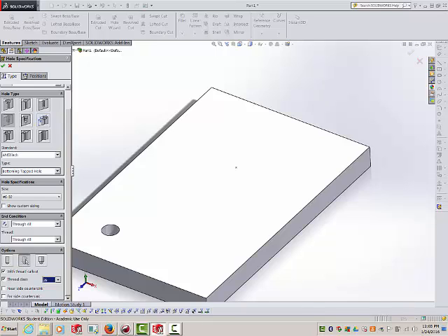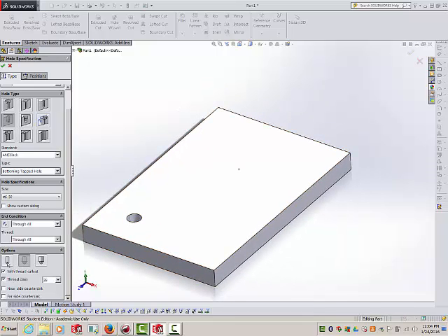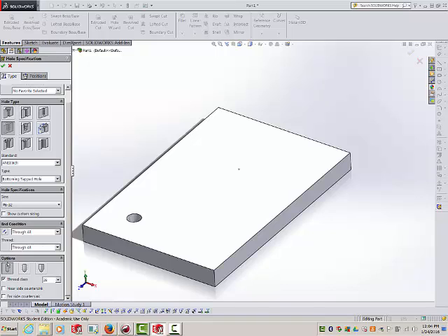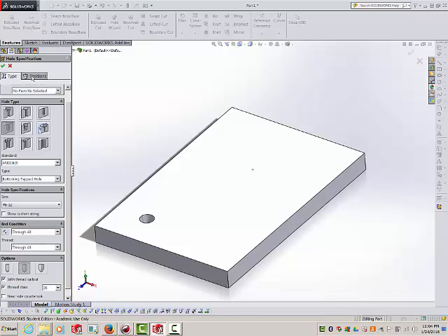I could do cosmetic or just the standard tap drill diameter, or removing the thread. It's actually not going to put the threads in here until maybe as we do the drawing print. We could show some of that as needed, or we could just show it as cosmetic. So drill tap diameter. So let's go ahead and go to positions.